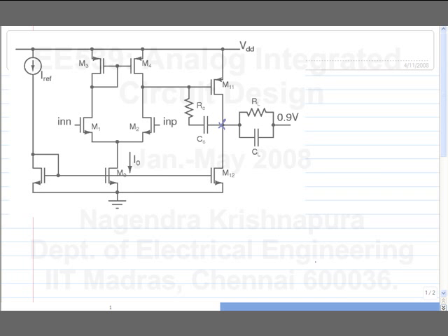So right now, what is the output voltage? Again, of course, the mirroring will be accurate only in quiescent conditions. The output swing is quite large. So that means that as the output swings, the current can be inaccurate. So let's fix it only in quiescent conditions. What is the quiescent output voltage? 0.9. Actually, it depends on how you put it in feedback.